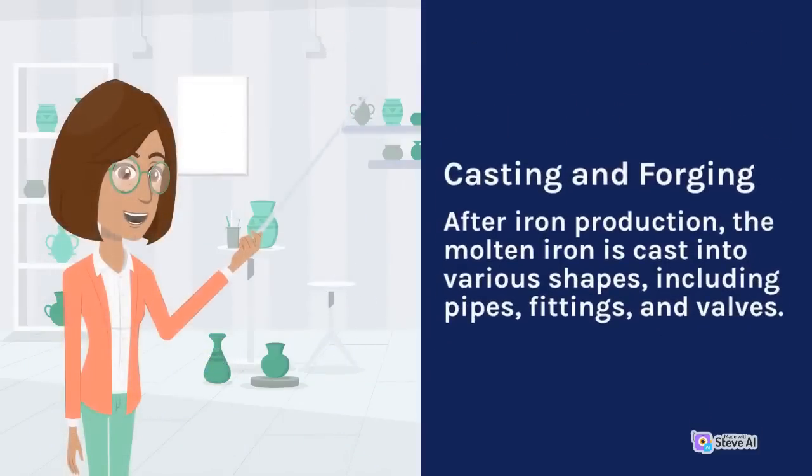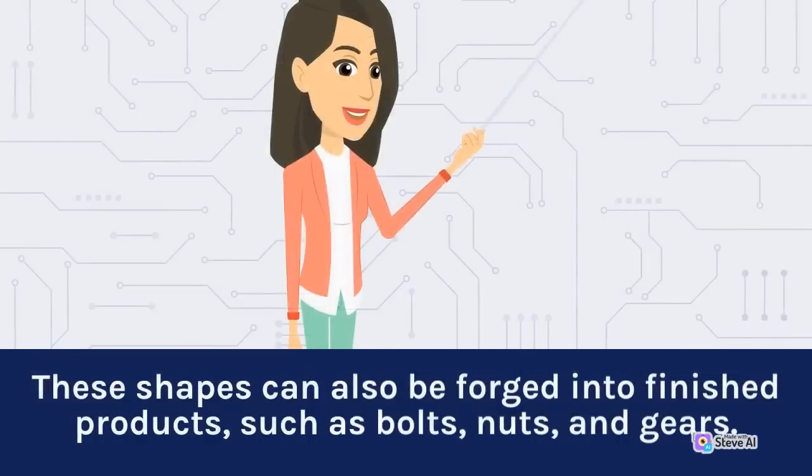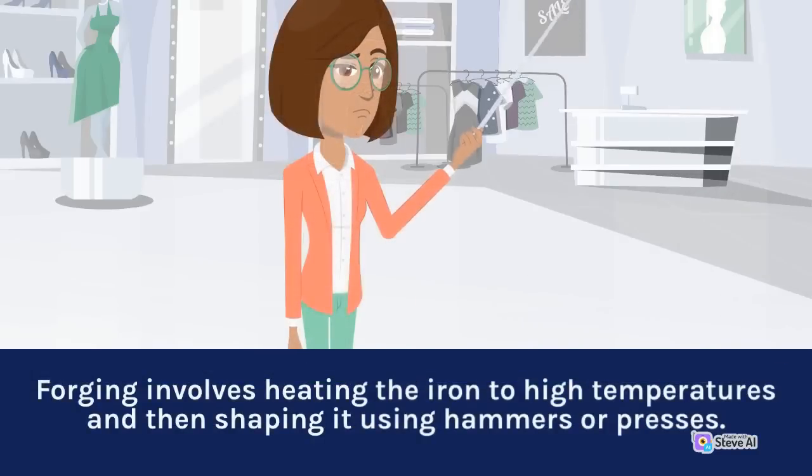Casting and forging. After iron production, the molten iron is cast into various shapes, including pipes, fittings, and valves. These shapes can also be forged into finished products, such as bolts, nuts, and gears. Forging involves heating the iron to high temperatures and then shaping it using hammers or presses.